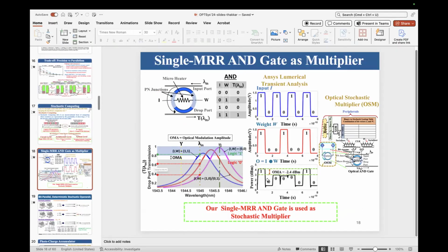This is still pretty rectangular, but not truly rectangular pulses. You will have to calibrate the area, the analog voltage that you get out of it, and based on that, decide what you want to keep the operating data rate as and what the widths should be.